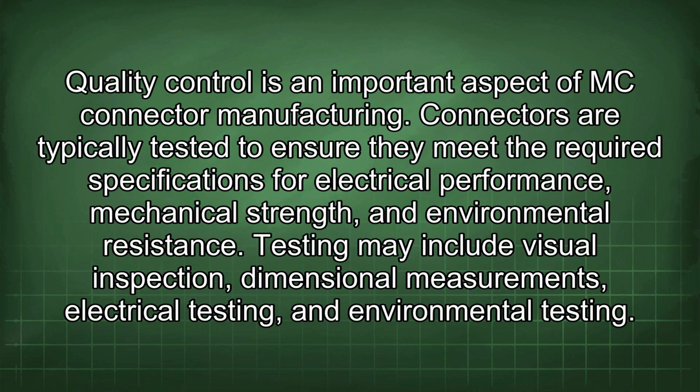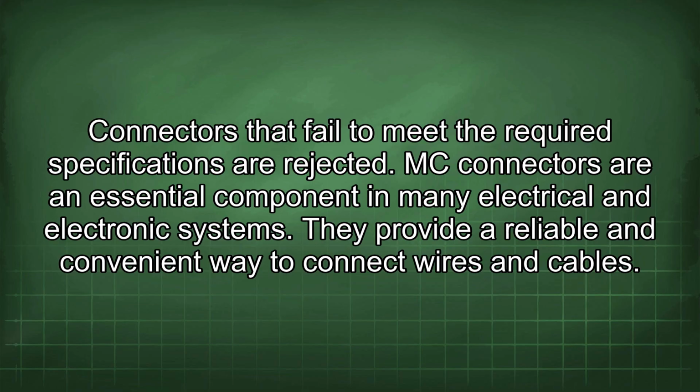Quality control is an important aspect of MC connector manufacturing. Connectors are typically tested to ensure they meet the required specifications for electrical performance, mechanical strength, and environmental resistance. Testing may include visual inspection, dimensional measurements, electrical testing, and environmental testing. Connectors that fail to meet the required specifications are rejected.